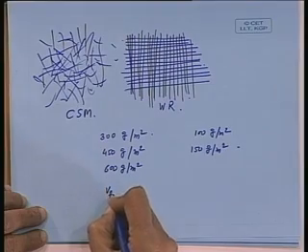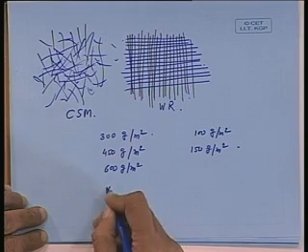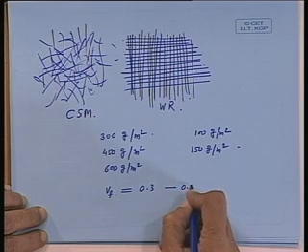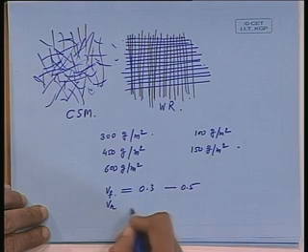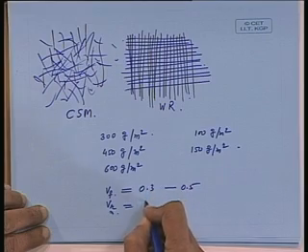So, when you make a sheet, you take a particular volume of that, and in that volume how much of glass fibers are there, that tells us what is the volume fraction of this. Usually we will find that the volume fraction of glass, that is the fiber we say, noted like this, is of the order of say 0.3, and it can go up to maximum 0.5. And volume fraction of resin, either resin or matrix they say, is